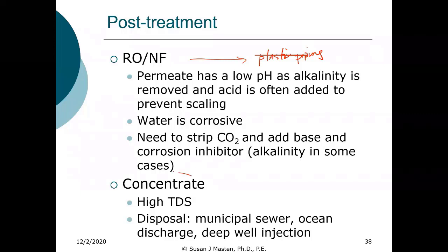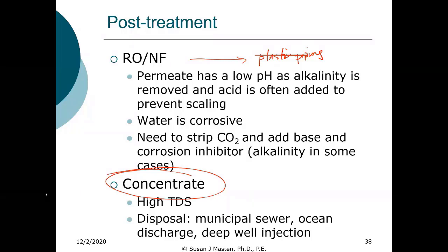The other challenge is, what do we do with this concentrate? It has a high total dissolved solids. We potentially can discharge it to a municipal sewer, but we need to be very careful with that, because if we change the salinity of our water, that has an impact on microbial growth.